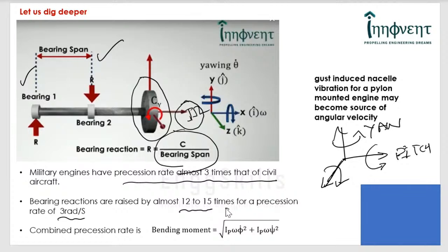And this is the effective gyrocouple that you can calculate. This is because both yawing and pitching are about 2 perpendicular axes, and the resultant can be had like this. So it is not just the design considerations at the operating point, but during extreme maneuvering situations, the design assumes a greater complexity and becomes much more involved and challenging.